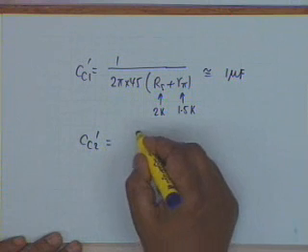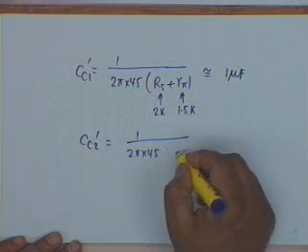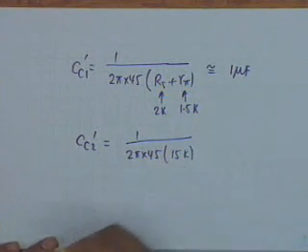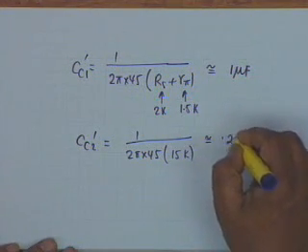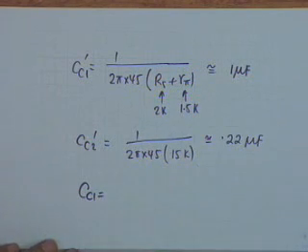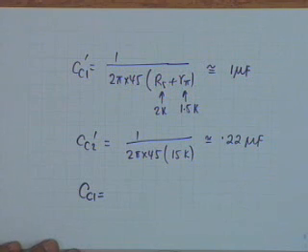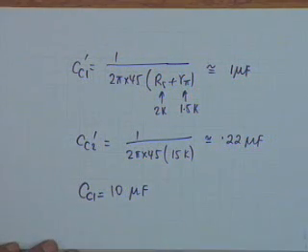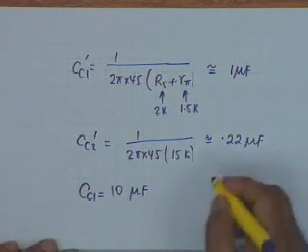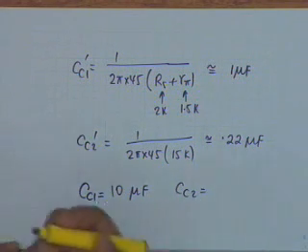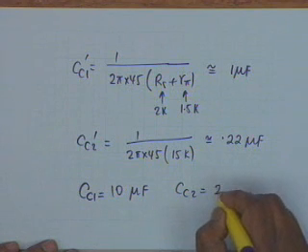Similarly, CC2 prime will calculate like this, 2 pi times 45, then RC plus RL, they are both given, so it is 15K. This calculates out to approximately 0.22 microfarad. So, in the circuit, what you use is 5 times this, 5 microfarad, you don't get 5, you get 4.7, or 6.8, use 6.8, use 10 microfarad, why not, even that is available, incremental cost, maybe a rupee more, which is worth it. And CC2, you shall use at least 5 times this, well 1 microfarad is a good figure, or slightly higher, 2 microfarad is also available, well use 2 microfarad.